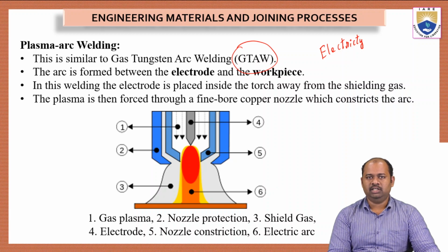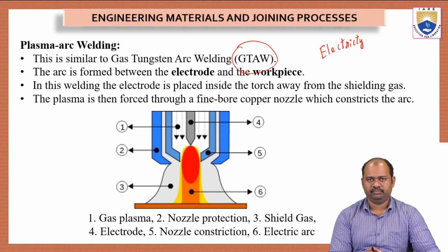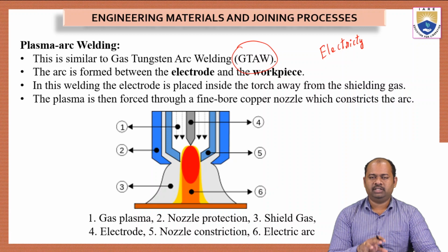Generally, in GTAW, the arc formed temporarily will be called plasma. It is only plasma for a few moments of time. But in plasma arc welding, the arc formed itself will be plasma only. So, in the entire process we can produce a constant flame of plasma arc.